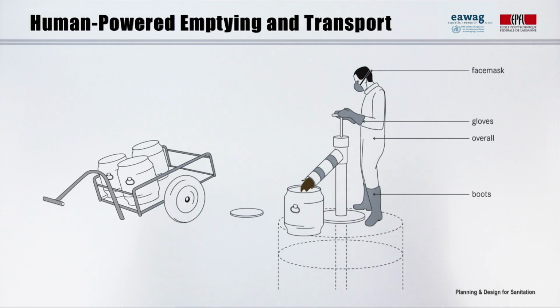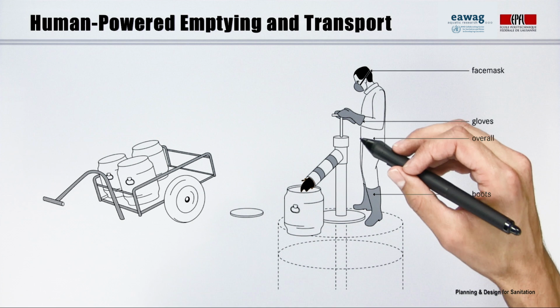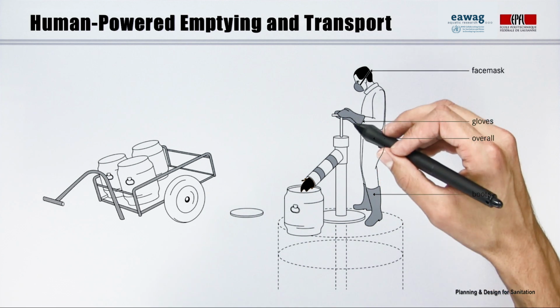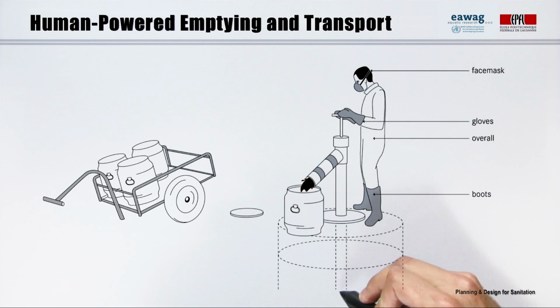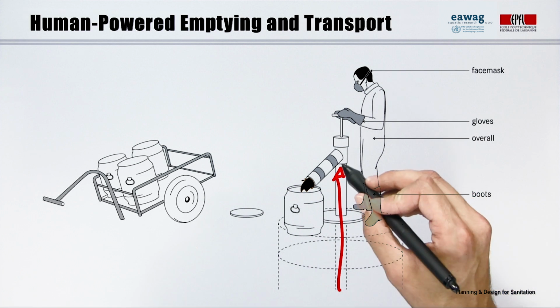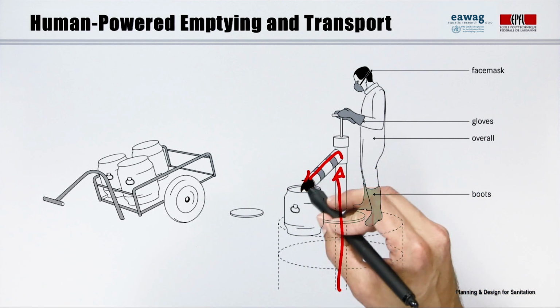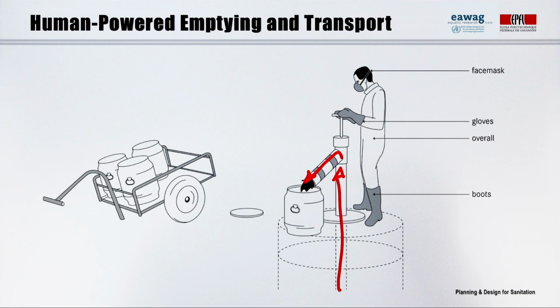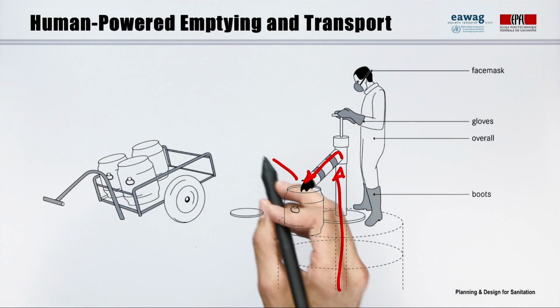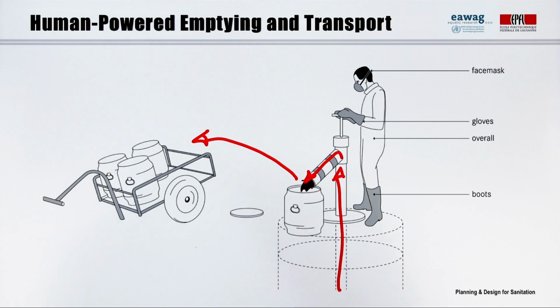Manual sludge pumps are relatively new inventions and are still being optimized. Sludge hand pumps, here the Galper, work on the same concept as water hand pumps. As the operator pushes and pulls the handle, the sludge is pumped up and discharged through the spout. It can then be collected in barrels, bags, or carts and removed in a quite hygienic way.